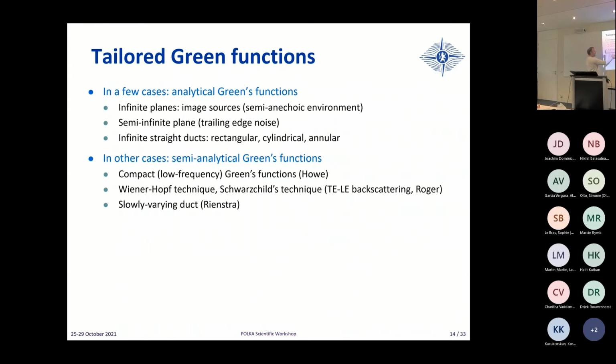If the acoustical wavelength is large compared to this radius of curvature, it will still look like a singularity. And then you have a backscattering problem, that is the one of the acoustic wave reaching the leading edge and being backscattered to the field. And then it's a semi-analytical approach because each step is an analytical solution, but each step is the predecessor solution for the next iteration.